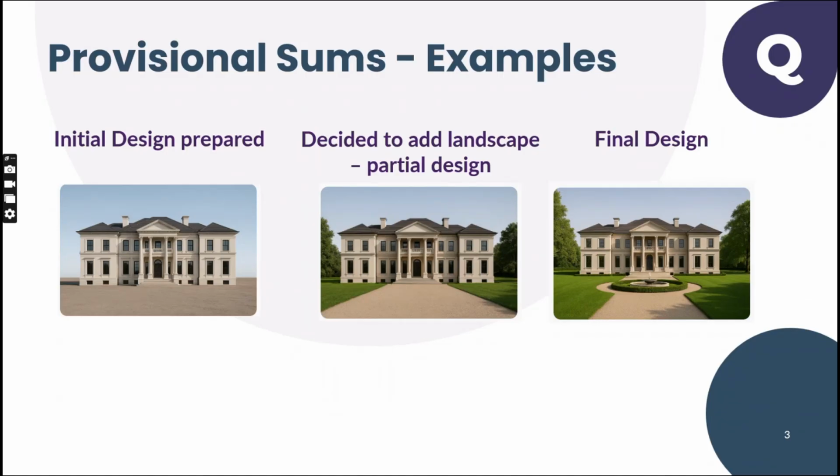There will be bespoke contracts concerning this, that's the bespoke only, but as per the standard conditions of contract, the accepted contract amount is excluding the provisional sum items, because it's provisional. You have not decided yet whether it is to be executed or not. So it will always have separate BOQ items. Okay.